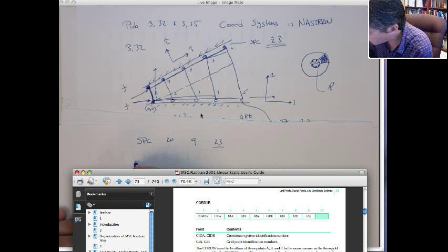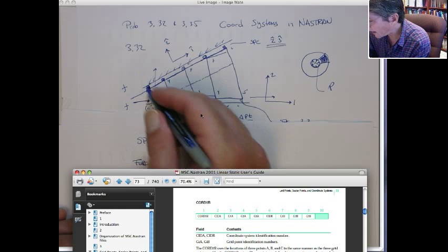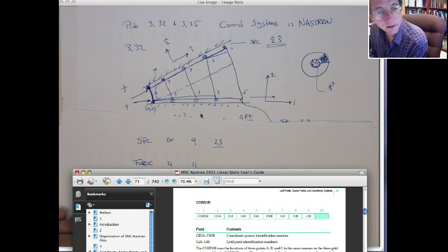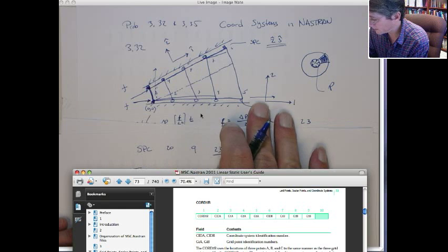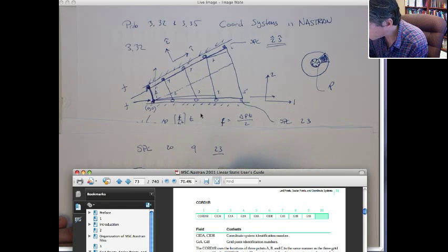And likewise, if I want to do a force, put in a load, set 21, at node 11, right? If I give it some value, I think it's the value first. First it's the value, so I'll give it like 100 pounds. That's the value.